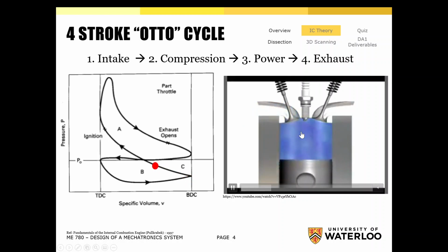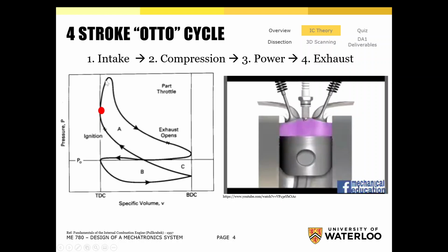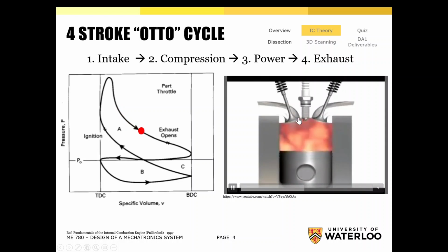This is where we are concerned with simulating, because the forces and pressures are going up within the cylinder. So this stroke here we're interested in simulating because the forces are very high, and then we ignite the mixture, combustion happens, and the internal pressure within the cylinder starts to decay because we're recovering all that work as the piston moves down.